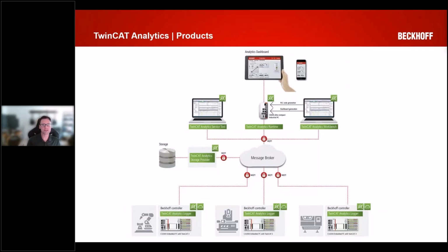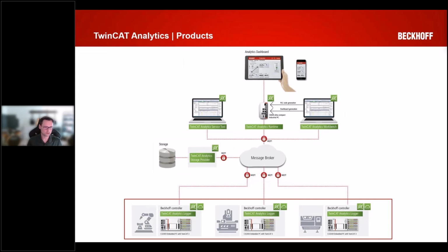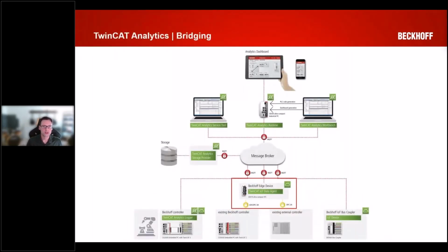There's a couple more little pieces worth talking about. One thing we did not address was if you're using third-party or legacy hardware. Now, not every PLC is going to be equipped with the analytics logger, which is seemingly a foundational component here. But if that is the case, you're using maybe third-party hardware, you do have options. So what we have here is a piece of Beckhoff software called the IoT Data Agent. And what that can do is act as a gateway and convert the OPC UA traffic, for instance, into MQTT to be able to tie into the rest of this workflow.